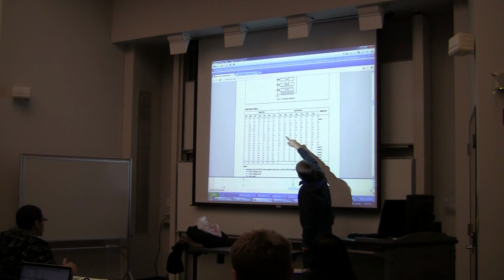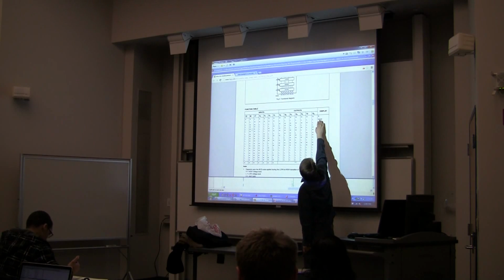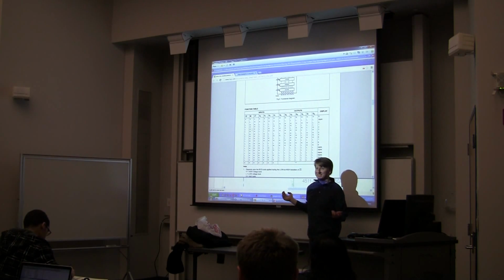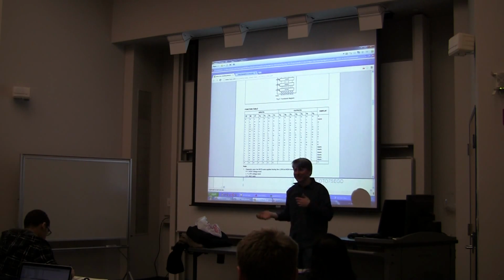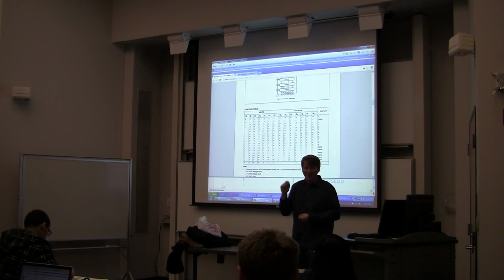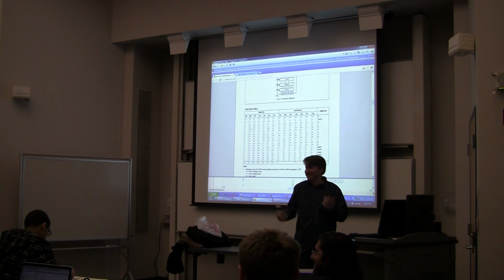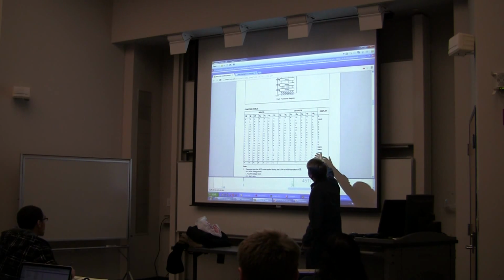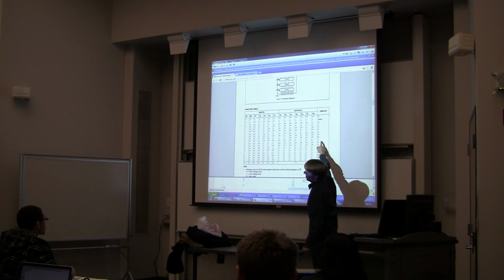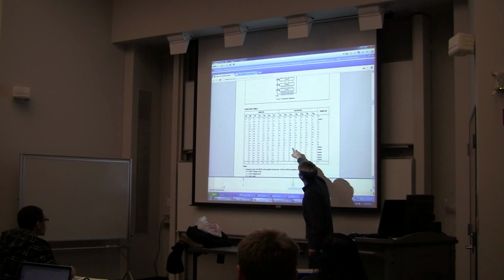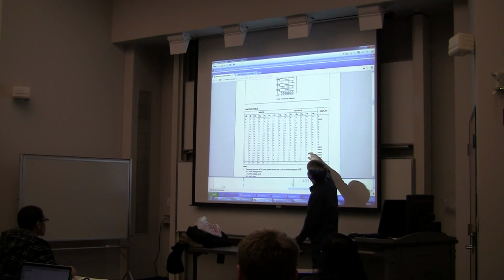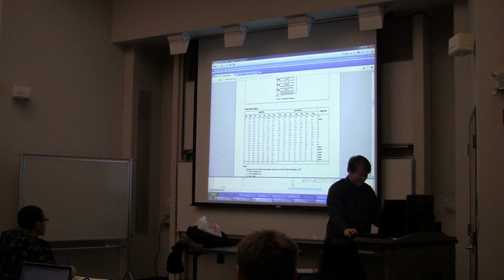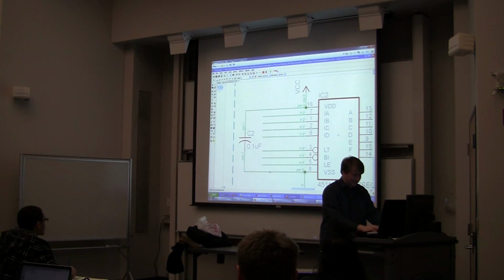Don't care. Also the LT one. If LT is low, it displays an 8 at all times. So if you really just want to display an 8, you could get away with just having one pin hooked up to this thing. If it seems a little strange to me, let us know. Hey, you can click 8s. So otherwise, this thing, when it's high, it does not flash an 8. Except in the 8 case, but that's because of all the other stuff. So I'm going to say that the LT thing is something we don't need ever. And I'm going to connect it to VCC so that it's always high.